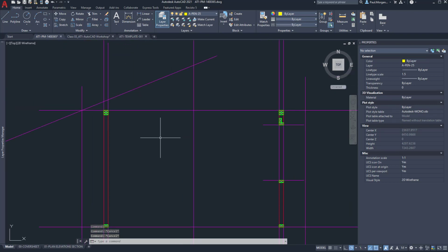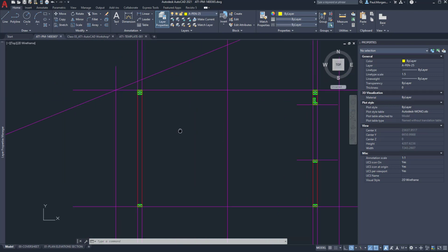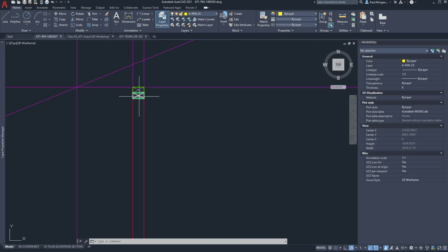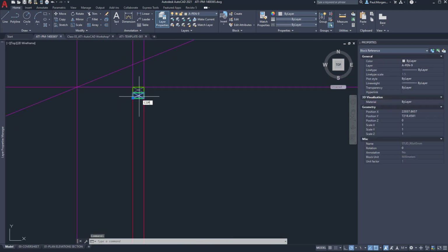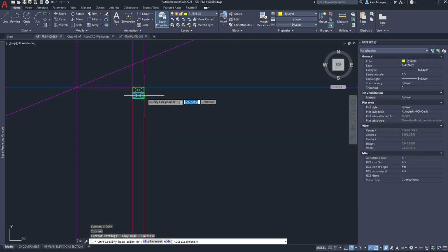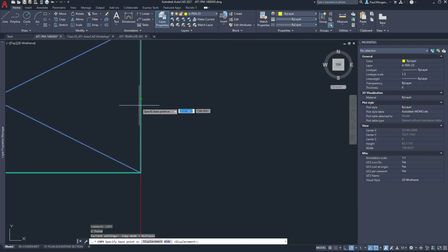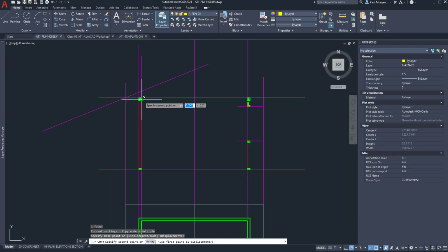Okay. So from here, we've got our stud walls on both sides. We can finish off our stud section by copying one of these stud sections and copying it from the midpoint of the stud on the outside, on the inside or outside, doesn't matter, and just hovering over the wall until we find the midpoint. So that's why we needed those red lines that actually showed the stud and projection, because these guidelines, they're different heights. They're not the height, so we don't know where they were going to be placed. With the red lines, we know that we were going to snap to the midpoint of the stud as where the nogging should be.